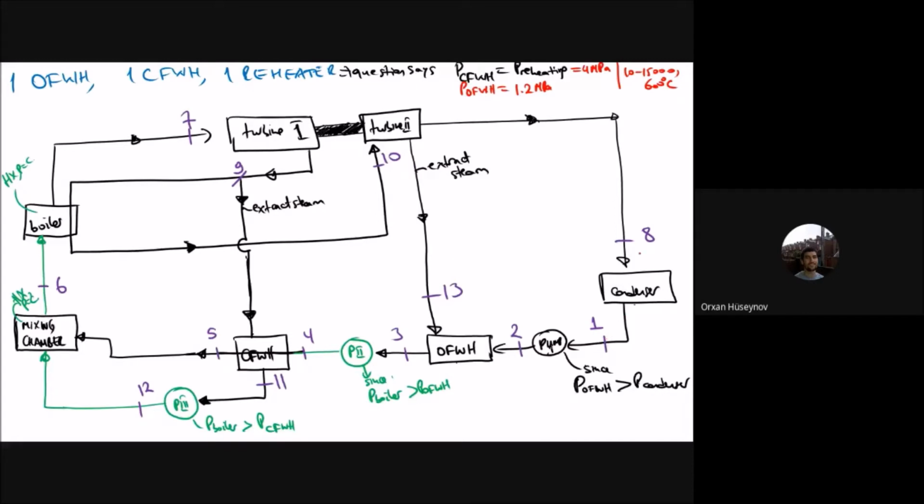So I will just start with the 1. The 1 has the same pressure as 8 because these are the heat exchanger. So P1 is same as P8. Okay. Now goes to 2. 2 has the same pressure as 13, and this one has the same pressure as 3. So you will have that P2 same as P3 and the same as P13. Because this is close, that is heat exchanger. Okay. And let me just draw this one here. These are connected. Okay, these are connected here.